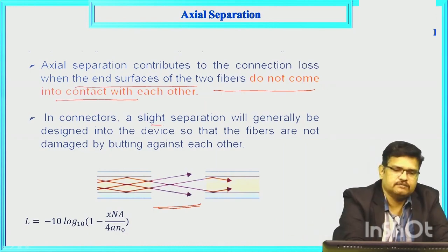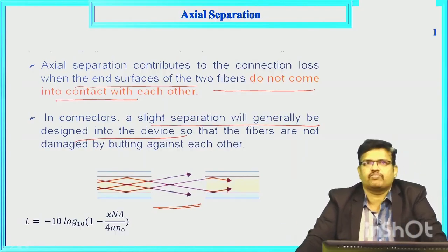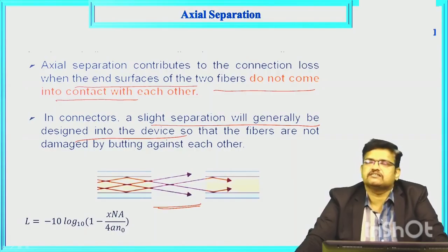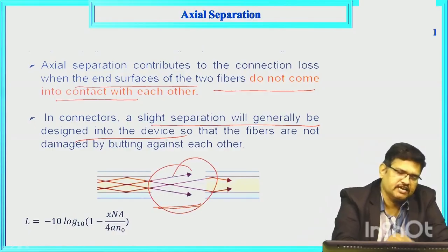The slight separation is generally designed into the device so that the fibers are not damaged by butting against each other. So this causes the axial separation. So here also we are experiencing more loss.